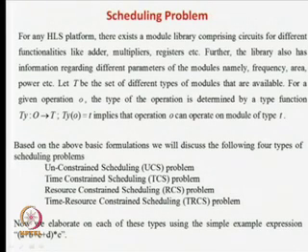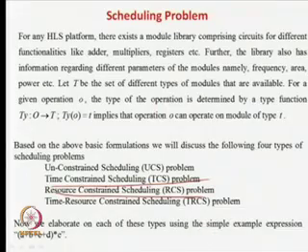The second is called time constrained scheduling. It says that you will be given a time constraint, that the scheduling should be possible in 3 time steps or 4 time steps. Sometimes you may get a successful result saying that yes, it is possible, and sometimes it is not at all possible, because we have given a constraint of 3 time steps and it is not doable in 3 time steps. Then there is resource constrained scheduling, in which time is not a matter, but we will give only one adder, one multiplier, one subtractor, and you have to reuse them again and again and schedule all the operations.